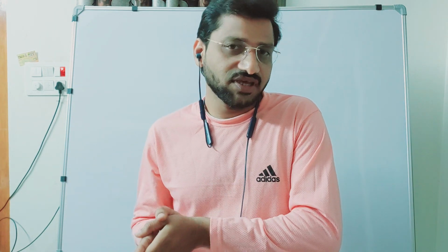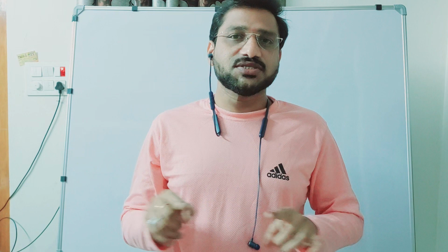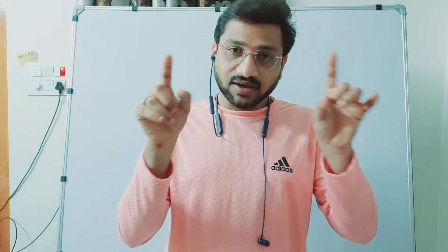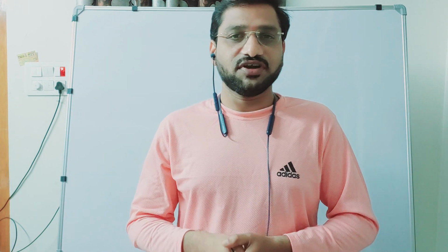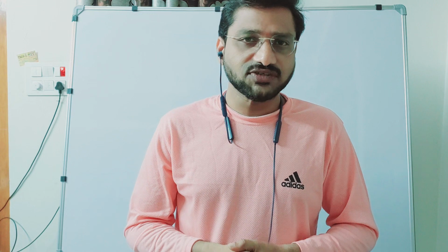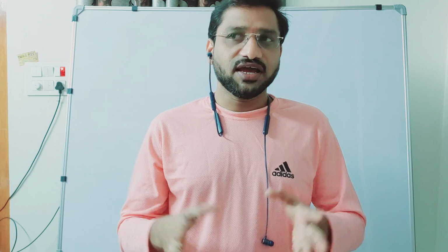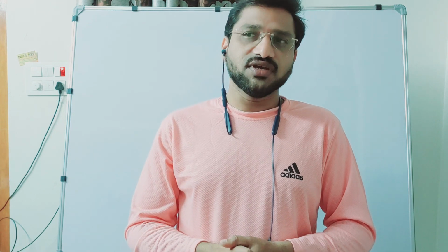So the AC electrical energy is fed to one of the electrical circuits, and this electrical energy will be transferred to the other electrical circuit without any physical contact, with the magnetic coupling acting as a medium. So this is the basic function and definition of a transformer, and the efficiency of the transformer is more than 98%, since it is not a rotating device, and the rotational losses are almost zero. It is having only iron losses as well as copper losses.